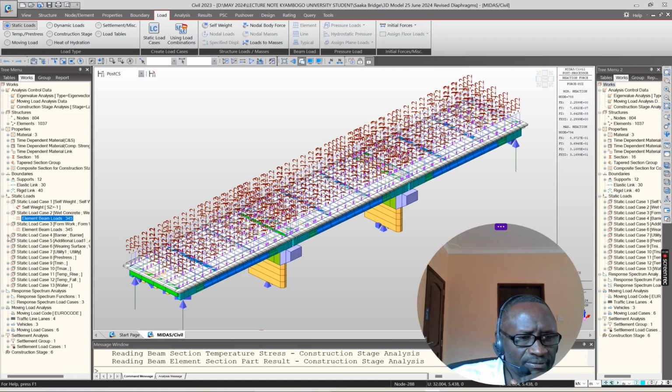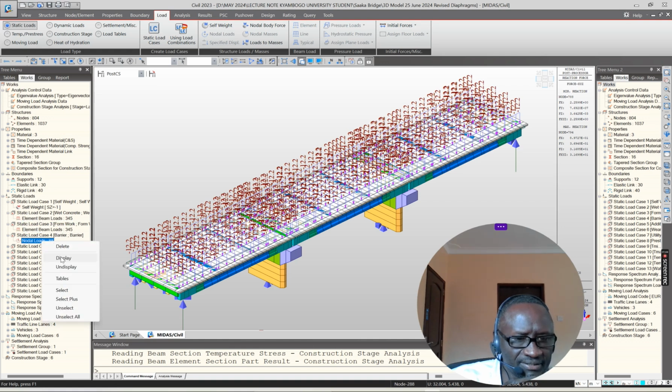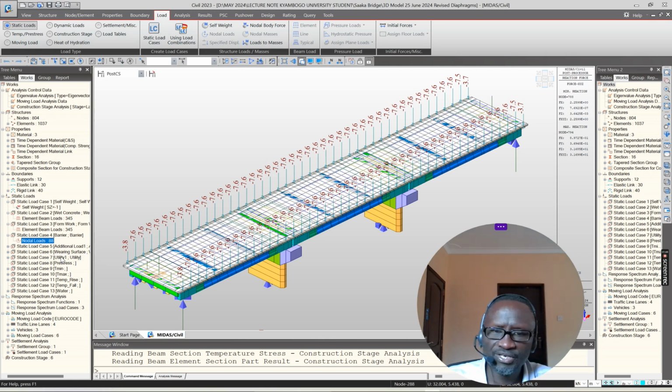And then you have the element of formwork I've given. Barrier loads, you can see how they appear on the edge. So you have your barrier load. You need to know the shape, the material component, and the unit weight. You have to calculate that.